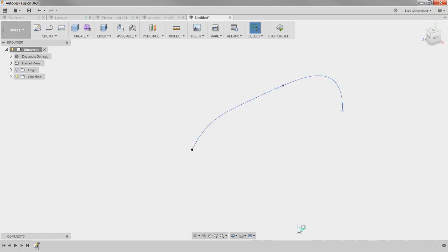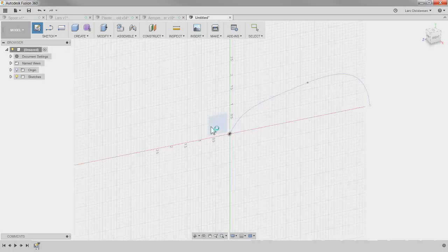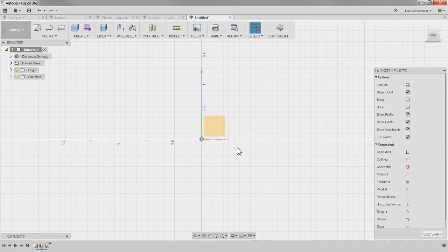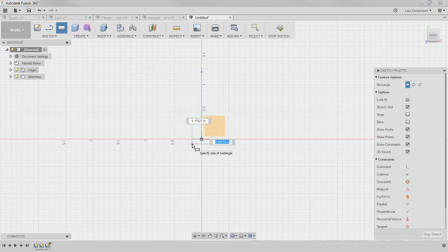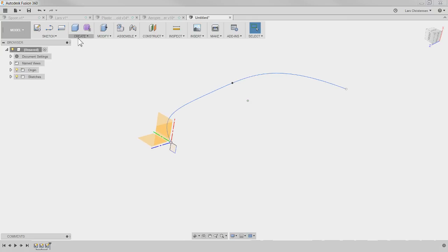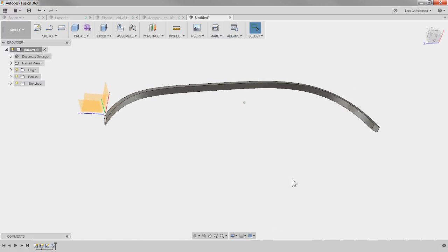And we have a handle in each point in here. So if I go in right now and create another sketch, so let's go in on this plane. Where do I want to go? Let's go in on this face here and create a sketch. And if I go in here and just create some, now I'm just freestyling a little bit. Create a little rectangle. And we, for example, went in and used something like a sweep. So we're going to select our profile. It's going to be the square here. And select the path. It's going to be this part here. So now we have this solid